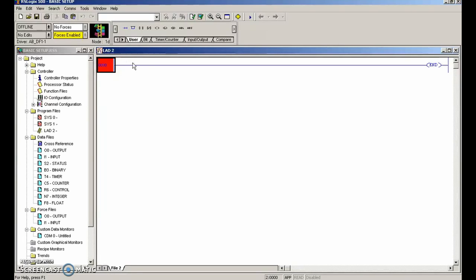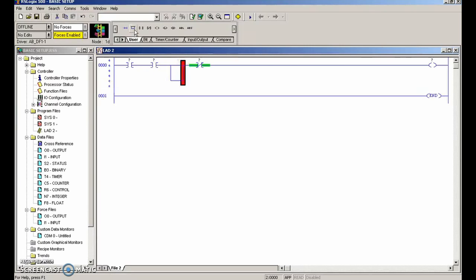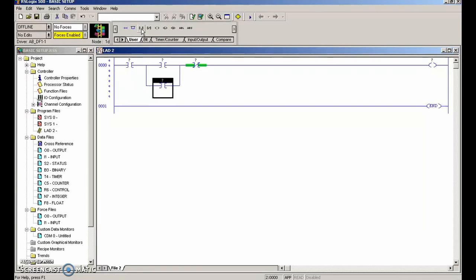So this is our end. We have to put in a new rung. And let's see, we've got the stop, the forward, the reverse holding contact, and then finally our output is the last thing to go on the right hand side. In parallel with the forward push button, we're going to have another examine if closed. Who knows why it puts it over here. We're going to grab this with the left mouse, bring it over till we see green, and then again we're going to highlight this side and drop in an XIC. Come on, buddy. There you go.